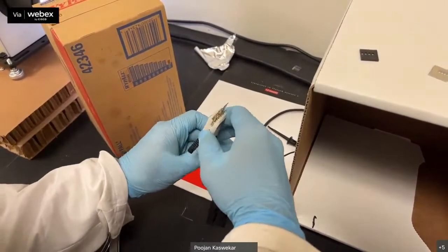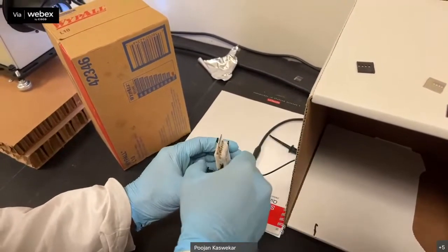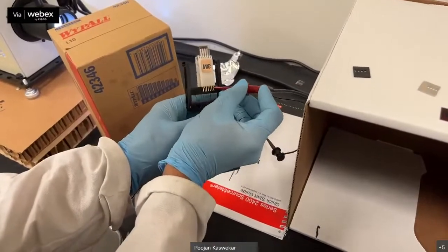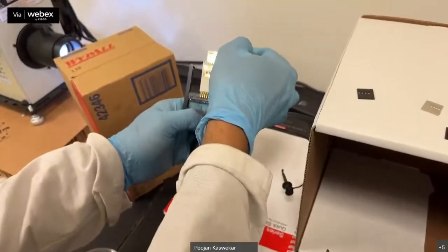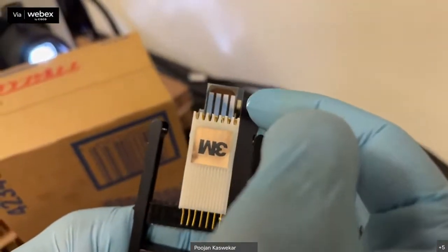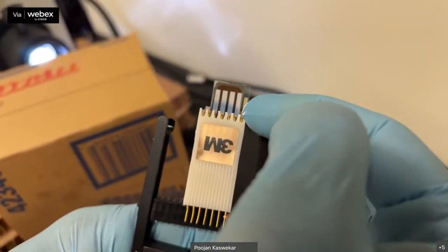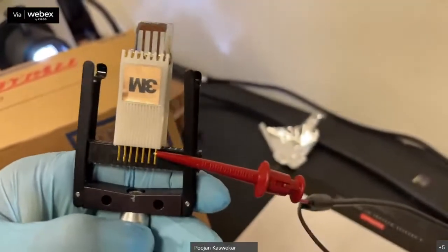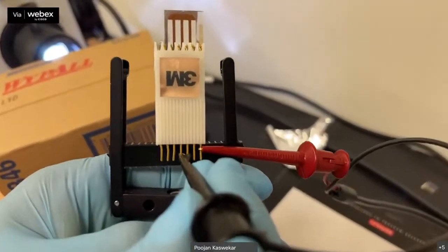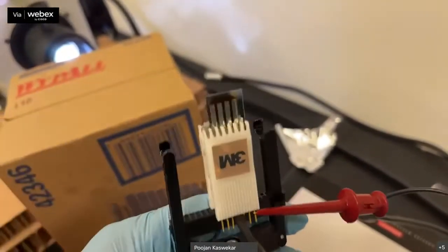Okay, and this positive goes to the first one. Yesterday somebody asked me why we etch this one. So this is the positive electrode for me. On top of the transparent electrode, the transparent glass, like ITO, we deposited an Ag finger. That is my positive, and the remaining four will be my negative ones. So I'm connecting in the third position, collecting current from my third finger.